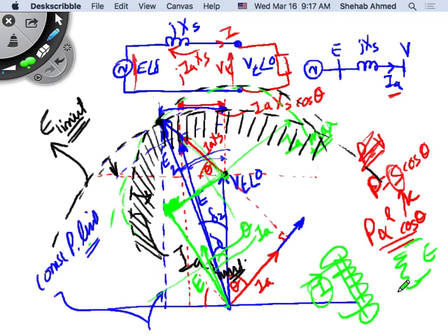So now it's amazing because at the terminals of the generator you have a high voltage, but you're not controlling it, because you're actually not controlling reactive power anymore since you turned off your field winding. So the field current, you turned it off. The field winding control circuit is called the AVR, the automatic voltage regulator. This automatic voltage regulator is a power electronics circuit that controls current, basically. So the AVR controller is going to turn off.